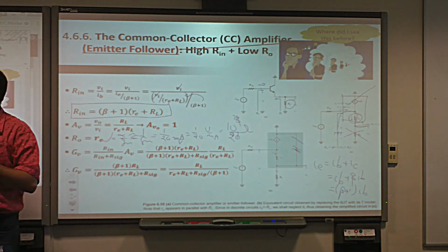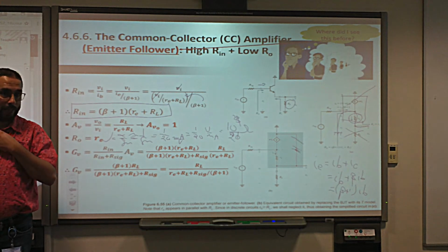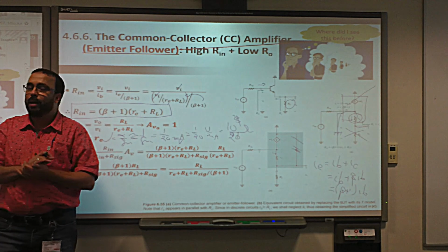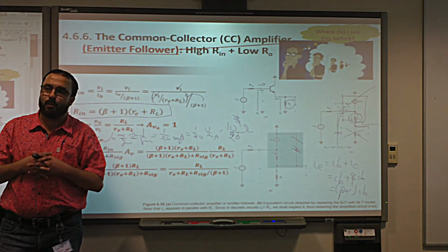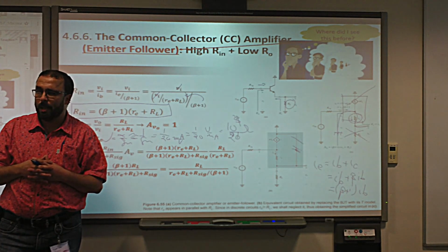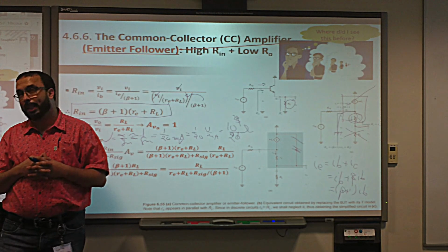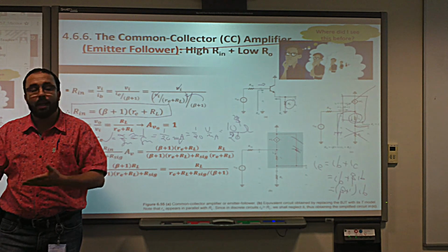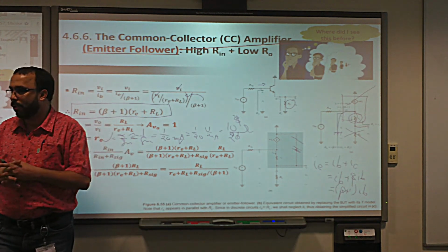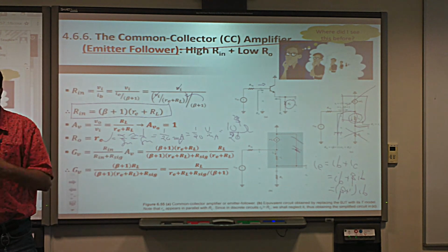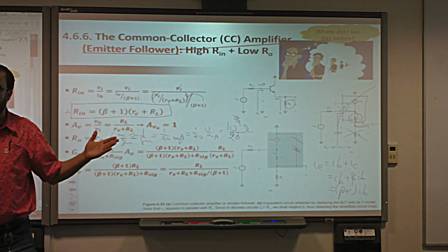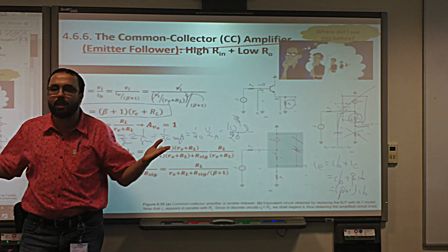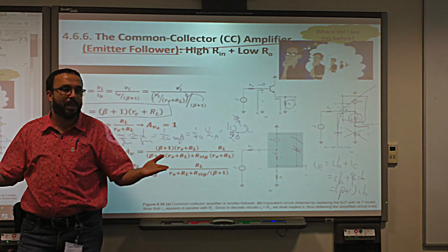Good. Now let's look at the voltage gain, the open voltage gain. To calculate the open voltage gain, we can do the same way that we did with the common source. No, with the source follower, which is common drain. We calculated the voltage gain with RL, and we made RL go to infinity. Because RL is part of the circuit, we cannot take it out. If we take it out, we cannot calculate. The current must go somewhere.